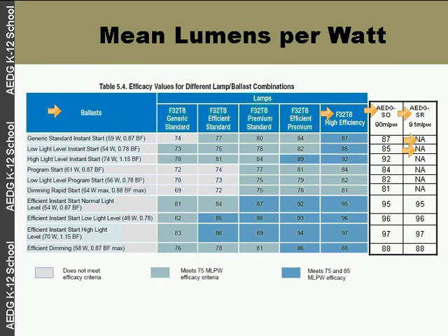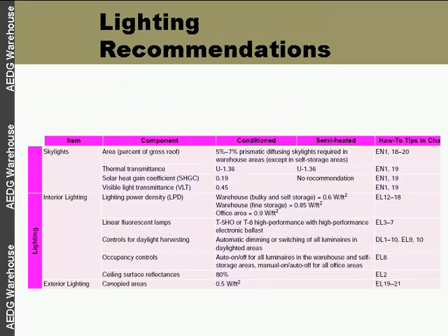Now, a lot of times when I throw out vertical, you're questioning what that is. A lot of times we'll talk about horizontal foot candles: light on the floor, light 2.5 feet up on a desk surface. It's the light that falls on those surfaces. Vertical foot candles we'll use in a situation like this where we've got stacks and we need to look 15, 18, 25 feet up in the air and read a label from that forklift and pull that product off of the racks. So that's the difference. We want to have 10 average foot candles on the face of that product, not on the floor. We don't really care how much light's on the floor.